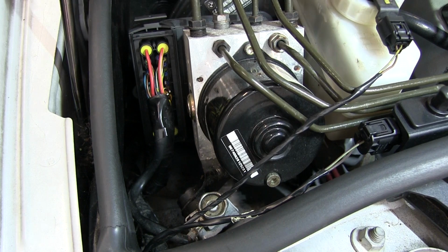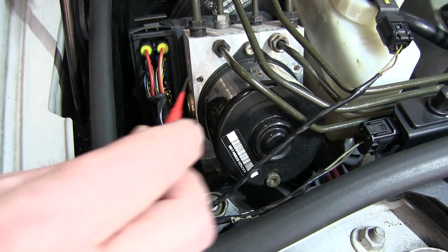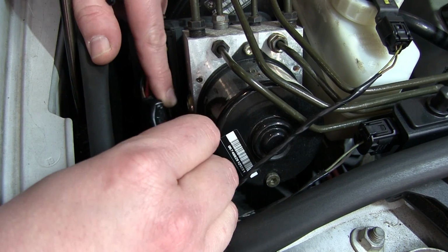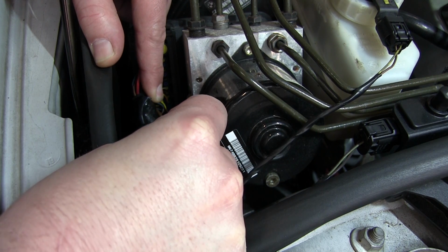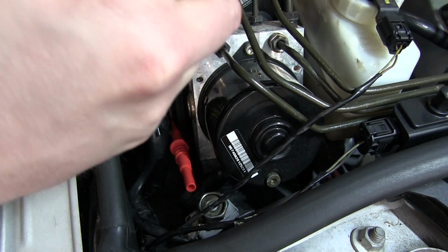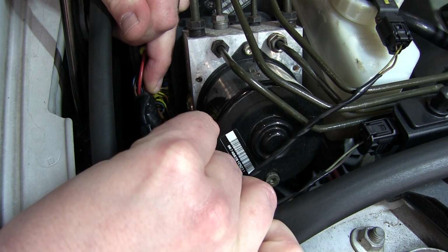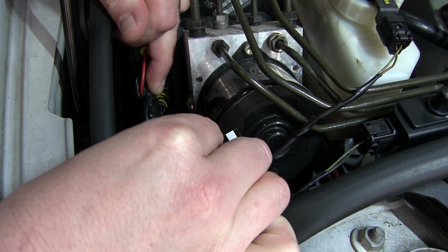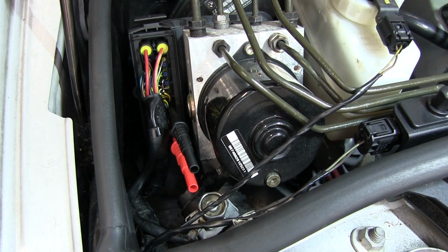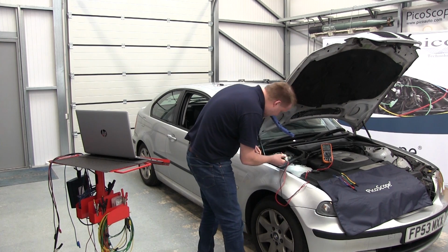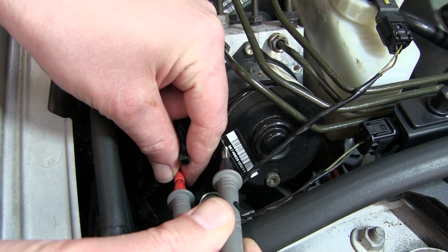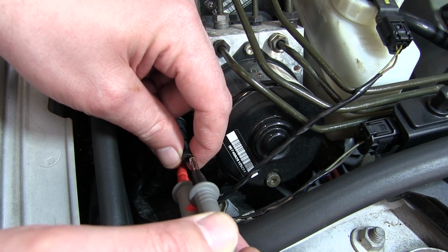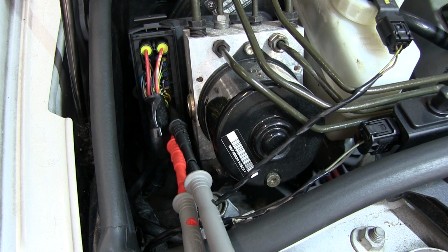So we take the two pins that we looked at before, the CAN high and low lines on the ABS circuit. So we've got CAN high on 15, CAN low on 11. Might be vice versa, but that's okay in this case. And again, back probing just for convenience here, making sure we're not damaging any seals or shielding. And with those in place, all I need to do is get our digital multimeter and look at the resistance.